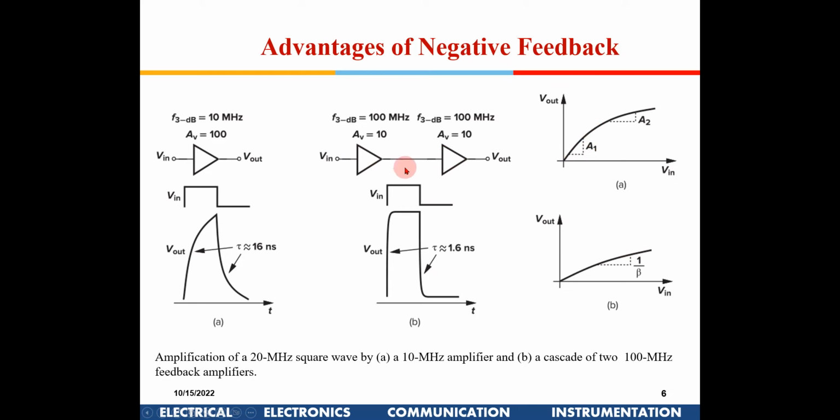So that is the second reason why we get a better waveform from these two cascaded stages with negative feedback rather than a single amplifier. Are the two reasons clear to all of you? Why does this non-linearity set in? Is it understood? Because all amplifiers generally have that input common mode range, right?